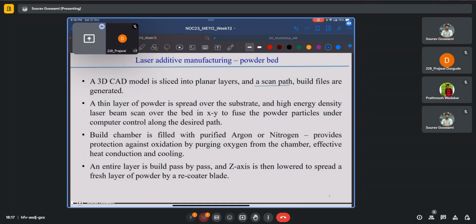Now, any powder recoating mechanism, such as a roller blade, a doctor's blade, or a slot feeder, can simply be used to deposit the required layer height of powder into the generated cavity, which will then be scanned by the laser or the energy source to print the parts in that slice.